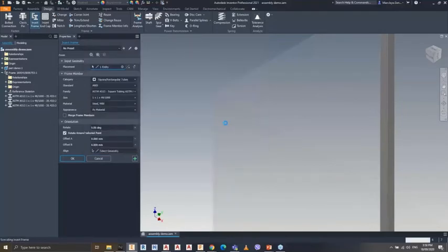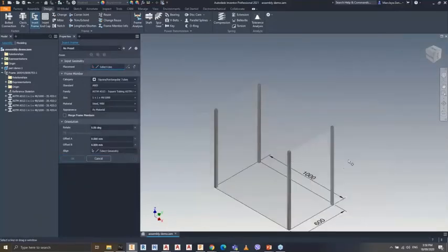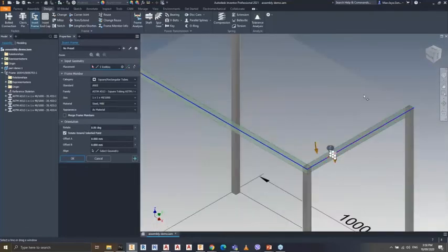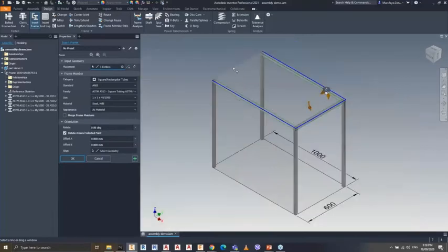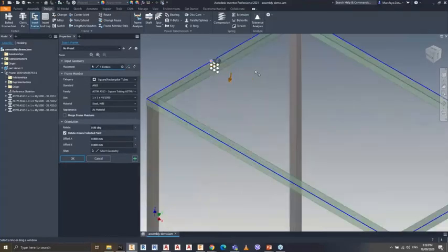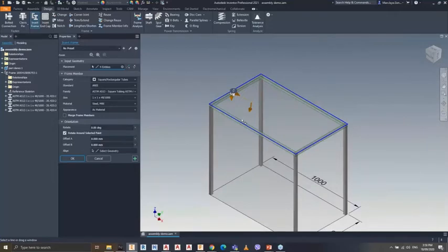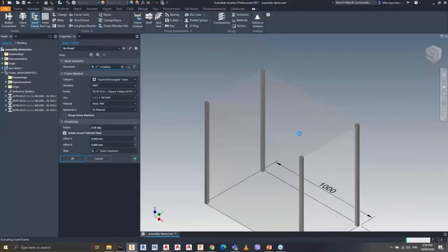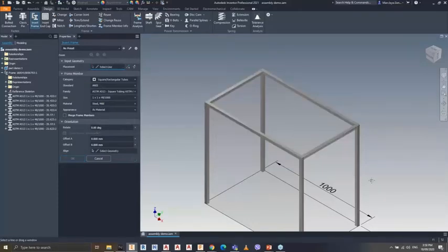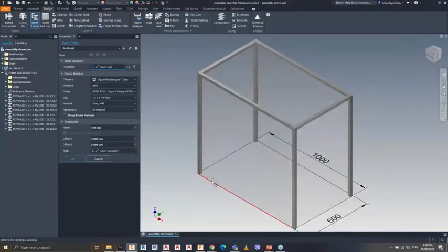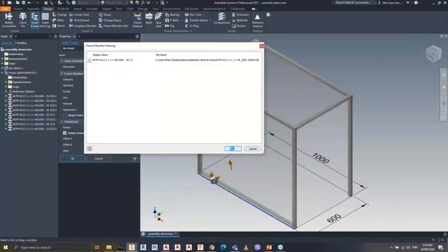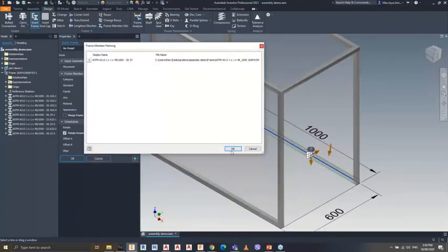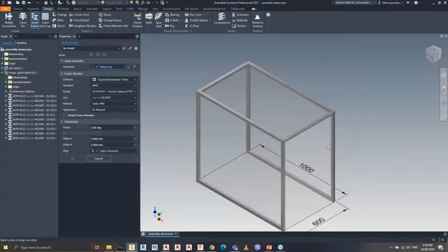Okay, so as you can see, I can model it directly using the Frame Generator of Inventor. Okay, it's not a problem even if it's my own design. Imagine if you were only using AutoCAD here, it would be a problem how to model that. So you can simply model it using the Frame Generator of Inventor. So maybe I'm going to add an additional model here for the framing of my table. Okay, so we have that now.